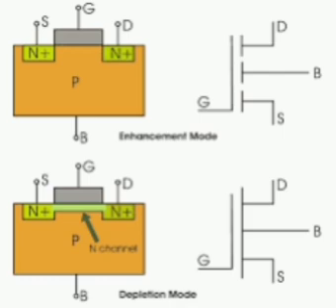For a linearly graded junction with the charge density increasing linearly from P region to N region as rho equal to alpha Q x, the depletion width is given as W equal to cube root of 12 epsilon V naught by alpha Q, where alpha Q is the denominator and 12 epsilon V naught is the numerator. Alpha means impurity gradient, Q means charge of electron, epsilon means permittivity of material, V naught means contact potential.